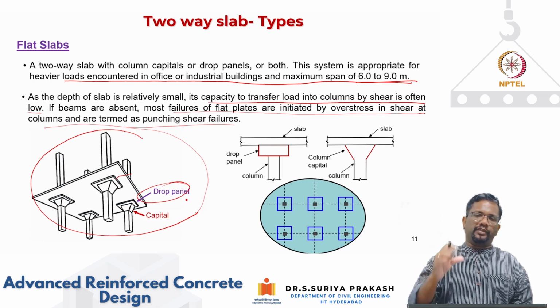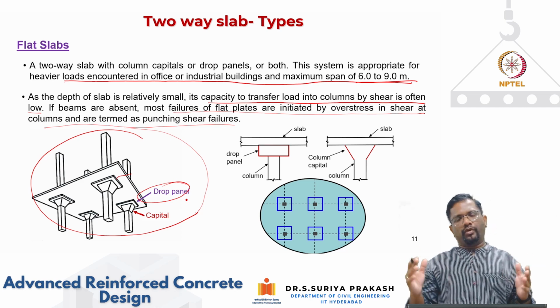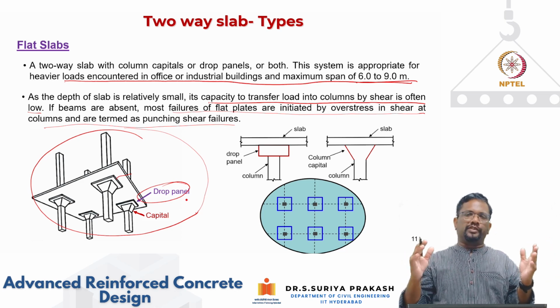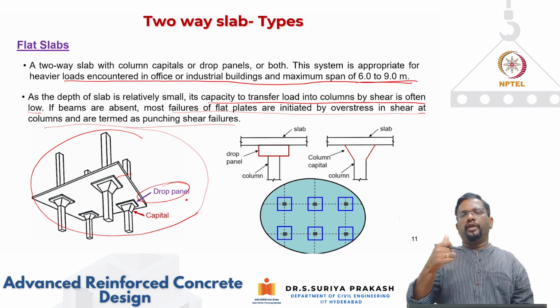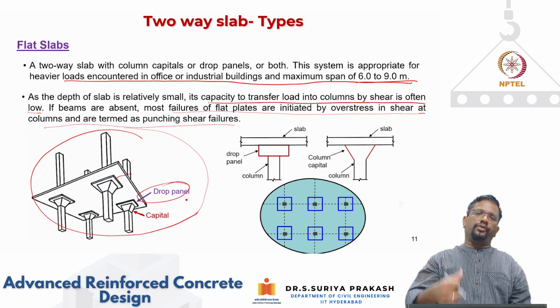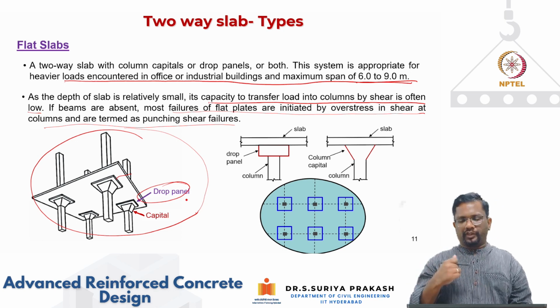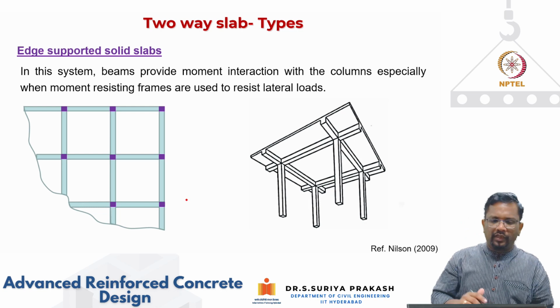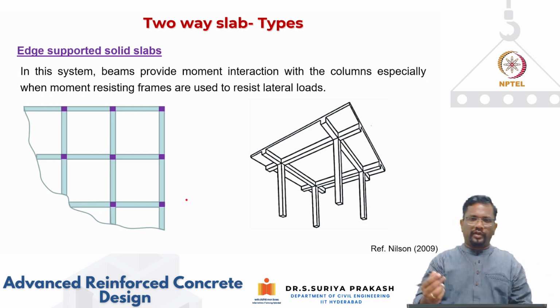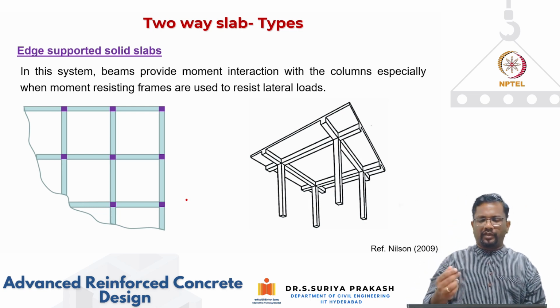There, with a very thin slab, still I can go for a longer span, and also the pre-stressing is going to help in improving the deflection and also going to increase your shear capacity. Right. So the next one is for a regular RC slab construction or cast in place concrete construction.